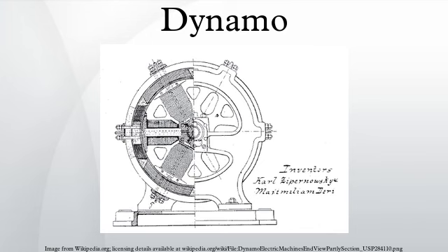History, development. The operating principle of electromagnetic generators was discovered in the years of 1831–1832 by Michael Faraday. The principle, later called Faraday's law, is that an electromotive force is generated in an electrical conductor which encircles a varying magnetic flux. He also built the first electromagnetic generator, called the Faraday disc, a type of homopolar generator, using a copper disc rotating between the poles of a horseshoe magnet. It produced a small DC voltage. This was not a dynamo in the current sense, because it did not use a commutator.